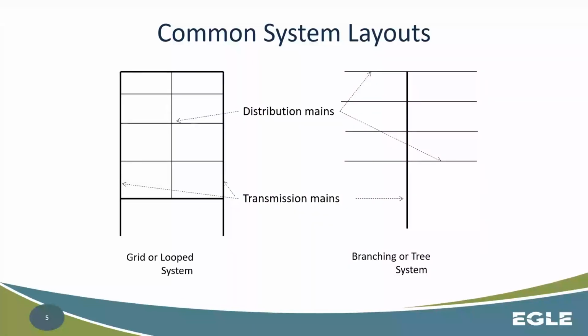And if, say, your distribution mains are slightly oversized or something like that, you have this stagnant water that's sitting there for a long period of time. It can lead to all sorts of things, whether that's biological growth, just aesthetic water quality in general, as well as corrosion issues. Deposits and sediment dropping out, and making those distribution mains fail faster, things like that.